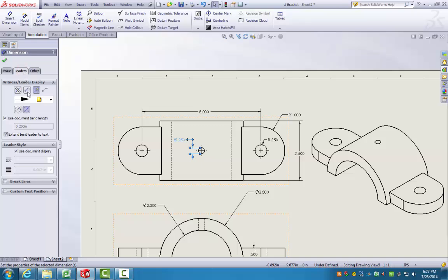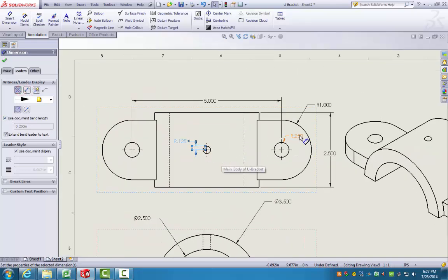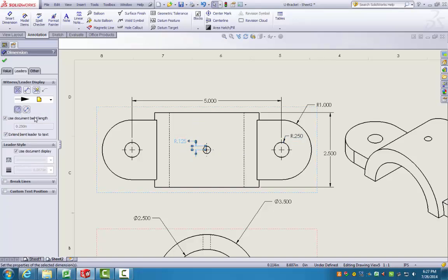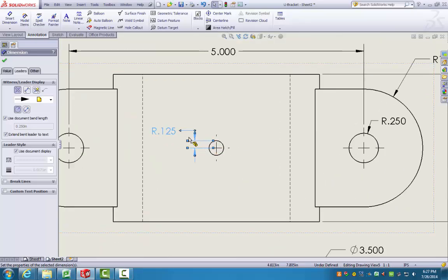We're going to try to do that same thing that we just did. We're just going to do a radius. And you can see that right now, if we go over here, this dimension is by default aligned, and we don't see that option. The reason for that is because it's from a hole wizard, so it treats it a little bit differently, because the hole wizard is all aligned, and it is a radius, but it's not a direct radius, and that's how SOLIDWORKS works.